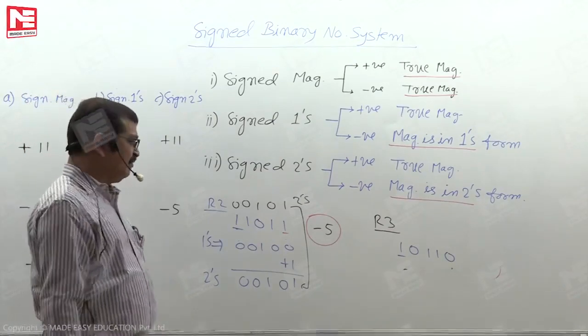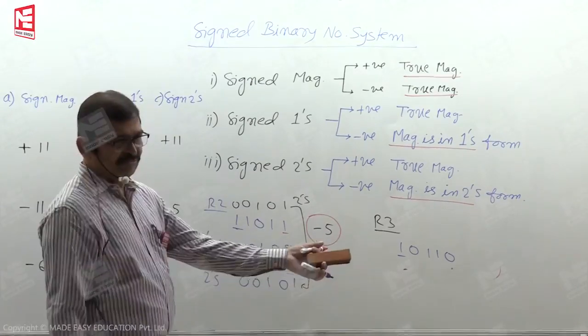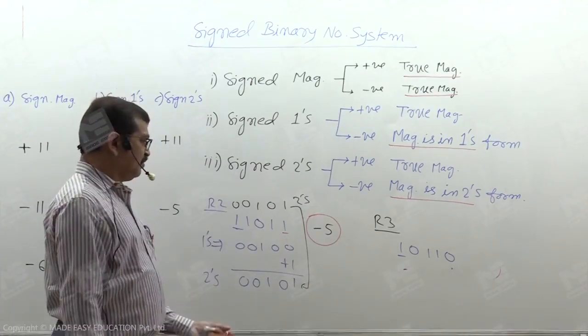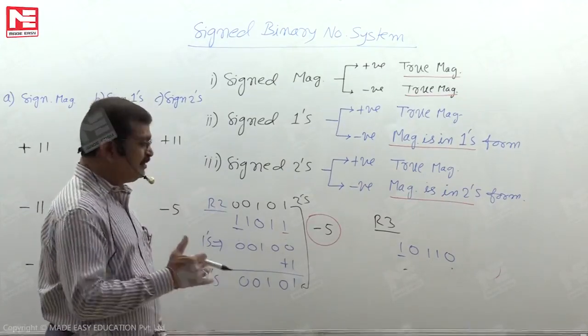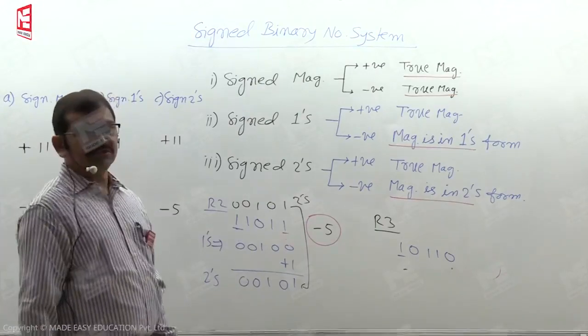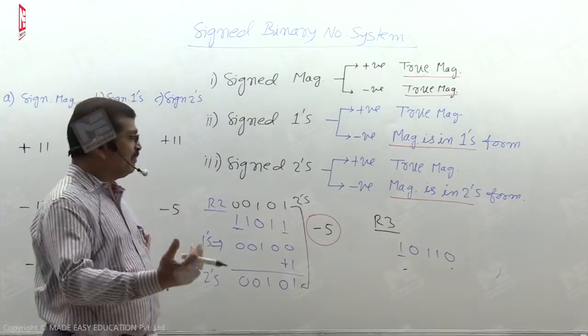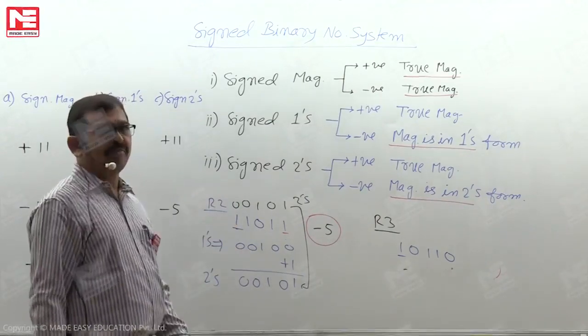It is useful whether the LSB is 1 or 0. We read the bits as they are until we read the first bit that is 1. Once we read the first 1, we perform bitwise complement. Then it becomes the 2's complement.